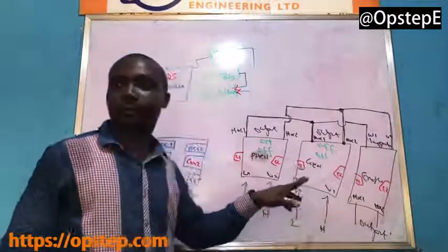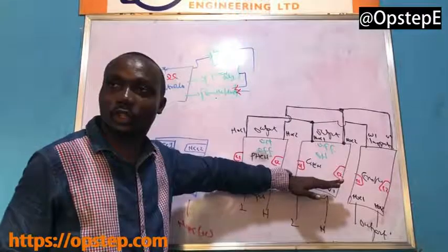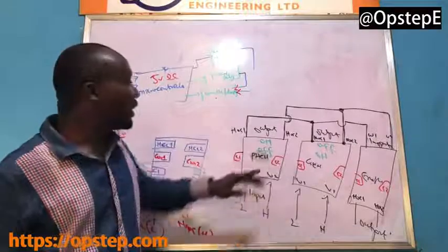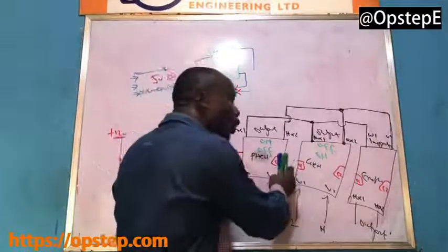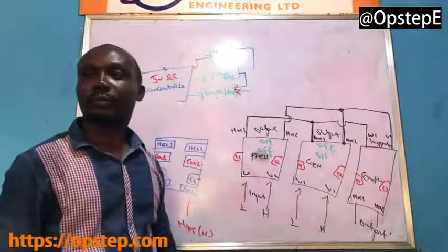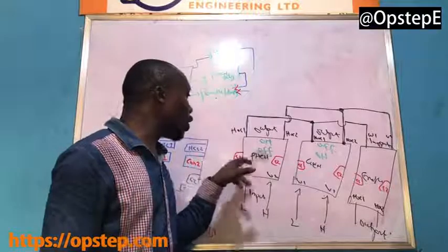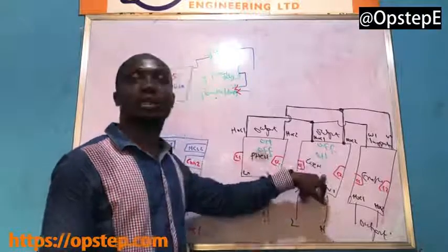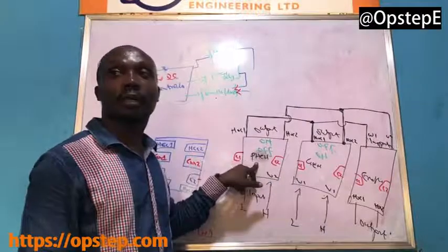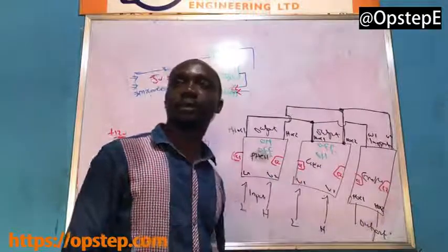NEPA can be available and generator can be on, and generator source is in here. NEPA can be available and NEPA source is in there. It is whichever coil is on that transfers to the need. So the way it's done is, if you need to on the coil of NEPA, then you off the coil of generator. If you need to on the coil of generator, then you off the coil of NEPA. And then you can on this coil for the enable or off the coil for the disable.